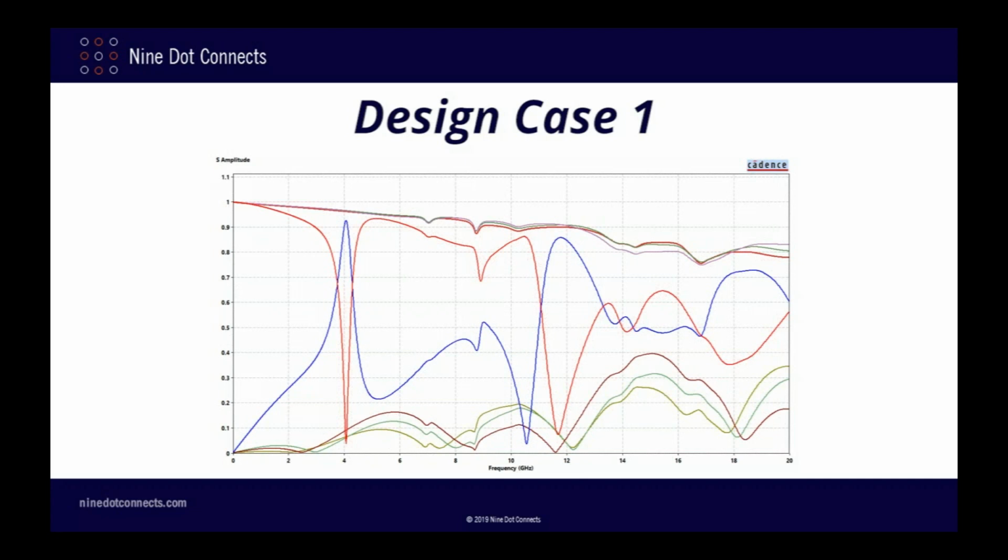So my answer to the question is that by changing the via diameter, I didn't just change the inductance, but I also changed a variety of other factors, all of which combine together and affect the overall impedance of the trace, and thus affect the signal integrity of the design as well. And as we see, lower inductance does not necessarily have a direct correlation to lower impedance. Rather, the impedance of the trace is a combination of a lot of different factors.